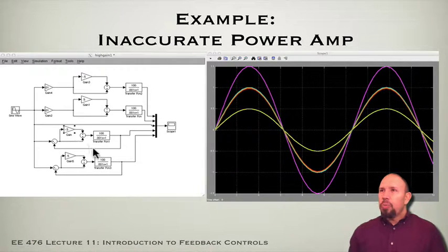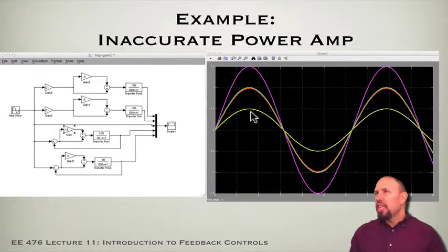Okay, and so when we actually look at the signal traces, we have the reference signal, which is a sine wave. Here what I see are what looks like 3 plots, and there's some overlay. The yellow is this top plot, the purple is the next one. This yellow has the minus, and the purple has the plus, and you can see they're significantly off. In fact, if you look at the peak values, it's still 50% off. This is plus 50%, this is minus 50%, so it's not doing that well.